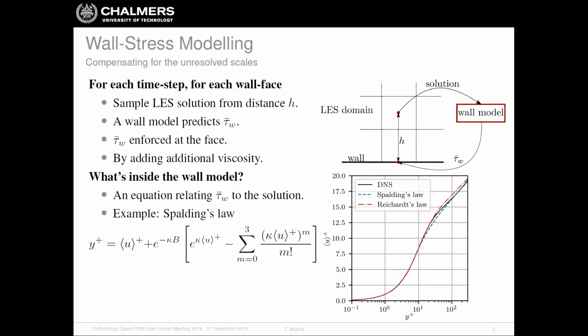The most complex wall models are based on partial differential equations. Then a little bit less complex are based on ODE equations. And then finally, mathematically, the most simple ones are based on nonlinear algebraic equations. And that's what we're going to stick to here. So we're going to use an algebraic wall model based on so-called Spalding's law.